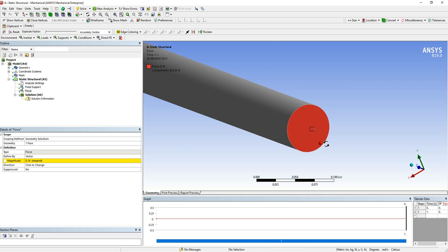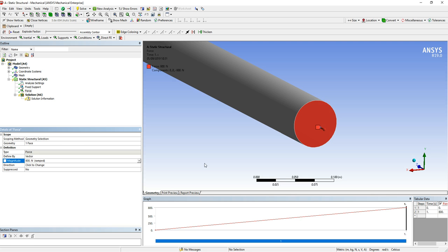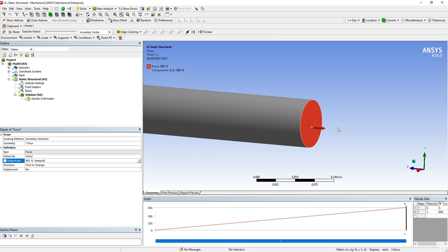And I'm going to go in the Y. I actually wanted to move in the Y component. I can go vector. If I go vector, and let's just say 800, so I'll go 800 newtons. Vectors are normal to the face that you've selected. Notice here you've got an arrow out. I can change direction, but only in specific points. So they're good for some things, a pain for others. I don't want to do that. I'm going to go component. You see where we got vector, got the arrow down. I'm going to go down to the arrow.